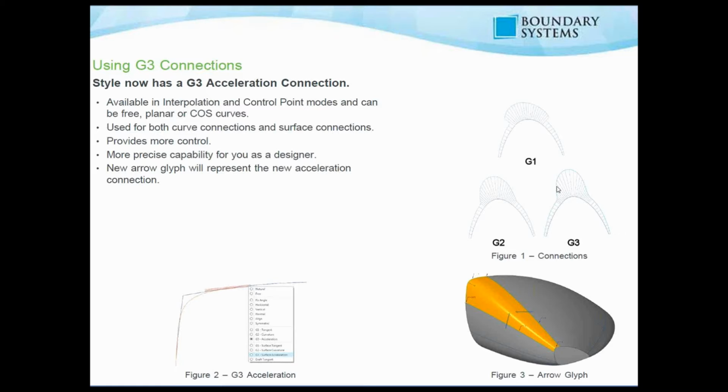Okay, so there is a limit of 5,000 control mesh faces imposed to be able to manage the file efficiency and retain the desired flexibility. So you can also flip the normal direction of the control mesh of imported geometry.